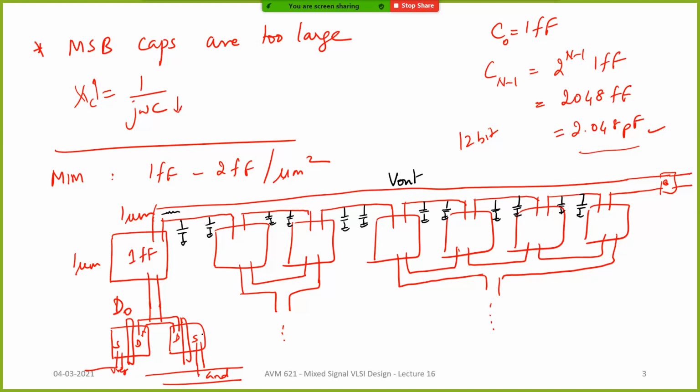Let's say for example this routing capacitance is totally coming to around 5 femtofarads. Effectively the capacitance on the V out line, connecting, let's say, an 8-bit DAC or something, is easily coming to some 5 femtofarad, or 10 femtofarad. So how does it matter whether 1 femtofarad gets connected to Vref or ground? It gets submerged in the parasitics.